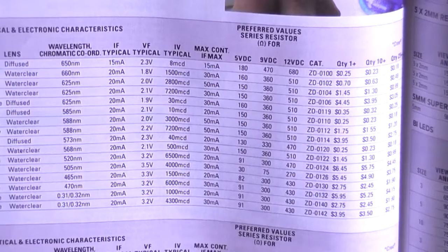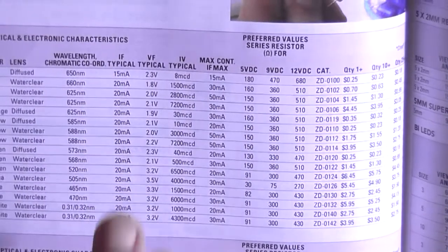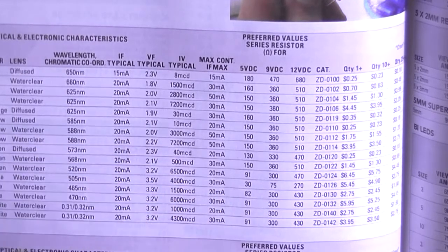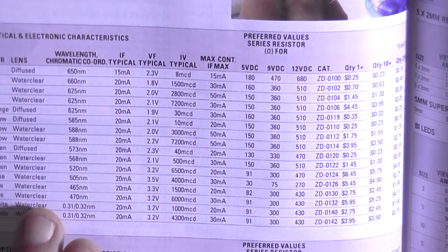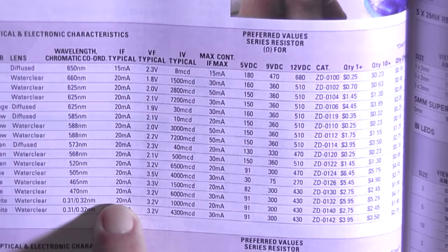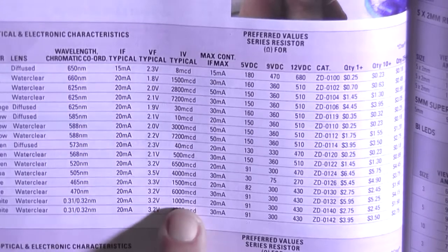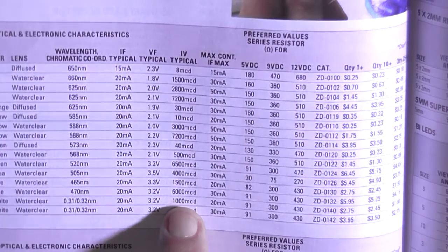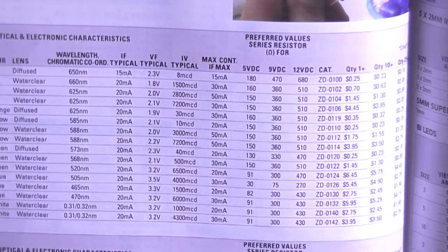Let's try another one. Of course, this is not going to help you if you don't have access to a JCAR catalogue, but you can probably find most of these figures, like its current draw and its operating voltage, from the supplier where you buy the LEDs from. Anyhow, I'm going to take a high brightness blue LED with its typical current draw of 20 mA, 3.2 volt, and 6,000 microcandelas. And we're going to use the 12 volt one again, so the figure we should end up with is 430 ohm. Let's see if we're right.